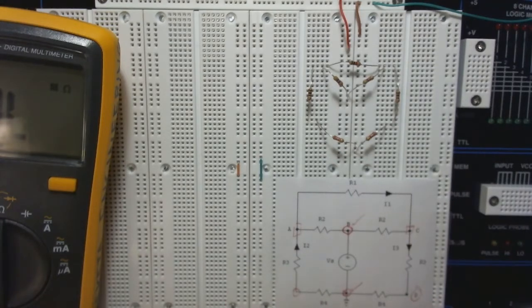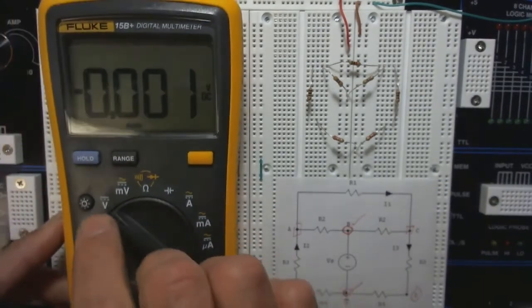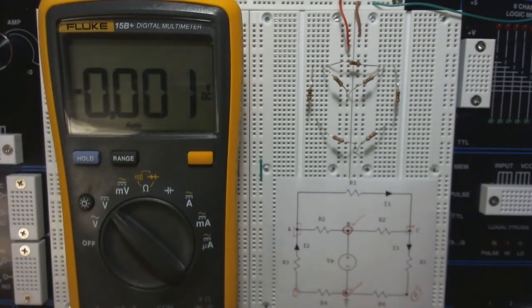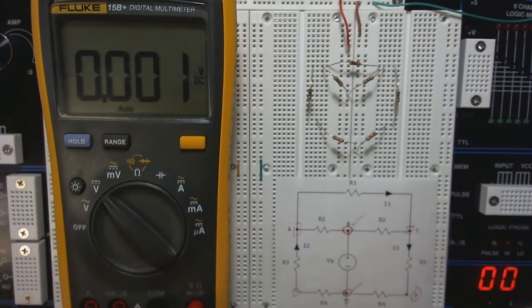So I think I've got it put back together after taking the resistance. I think I'm ready to go. I'll go ahead and power back up. I'm going to change this to volts, so put this on volts with a straight line so that I get the voltage when I'm measuring the voltage.